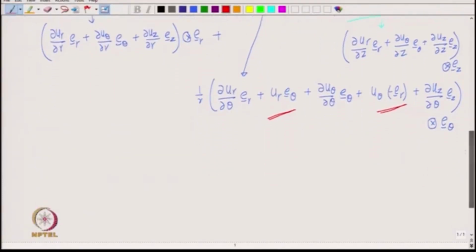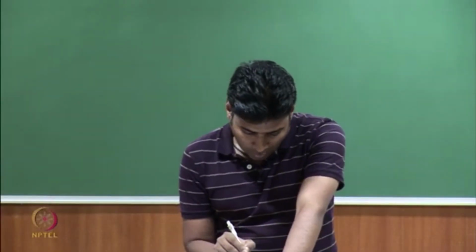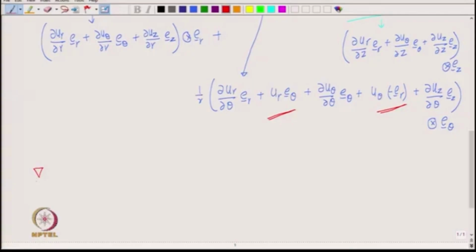Okay. So, when we work out the strain matrix, how to populate the strain matrix now? So, let us first work out the displacement gradient matrix. So, displacement gradient matrix in r theta z coordinate system. So, its first row first column, that would be the component of the basis E r tensor product E r.